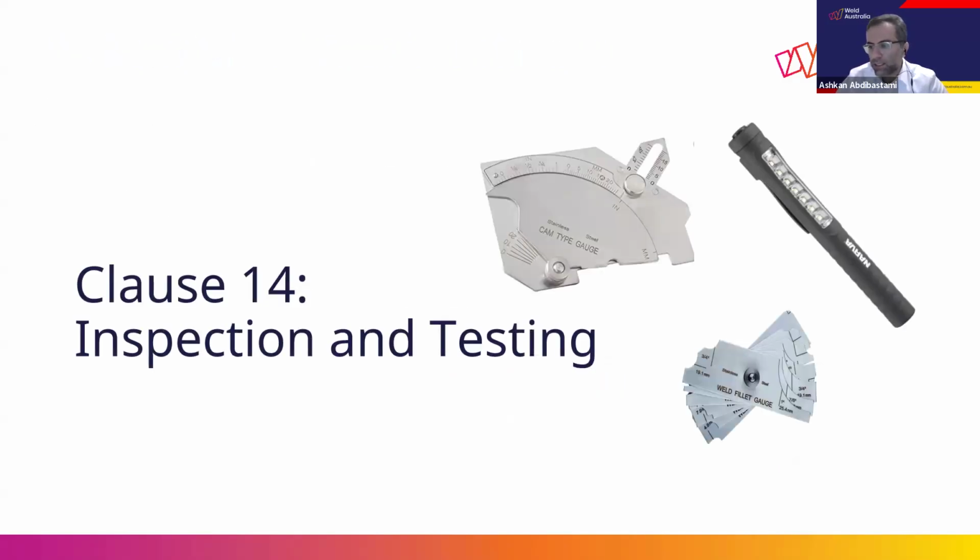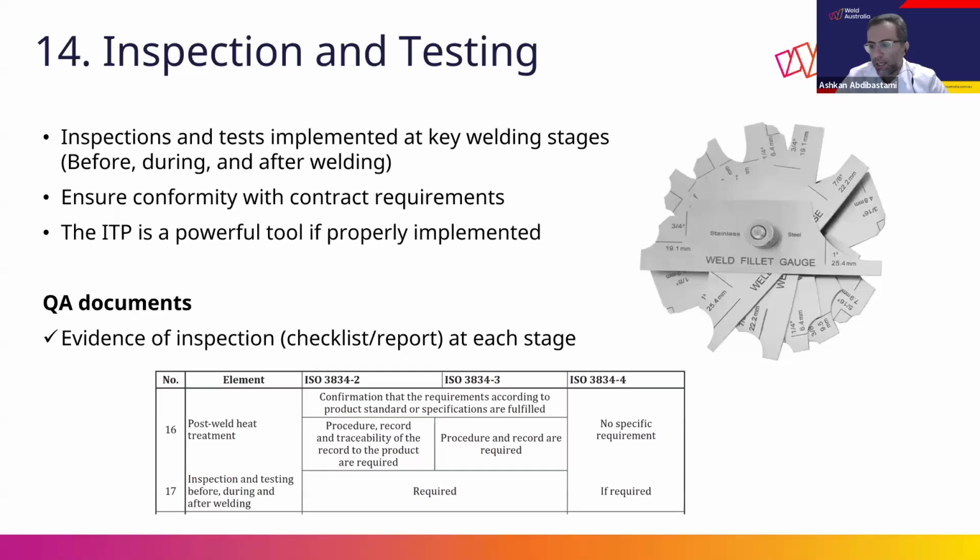Clause 14, inspection and testing. Inspection and testing need to be carried out at key stages, especially before, during, and after welding, to ensure conformity with contract requirements.